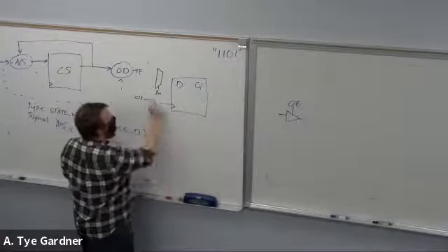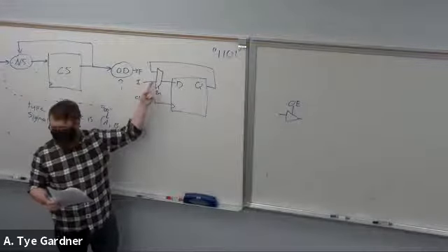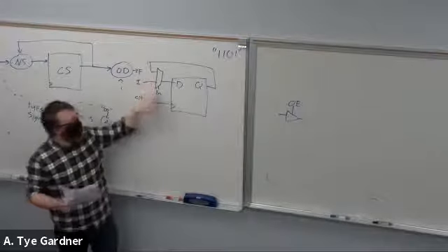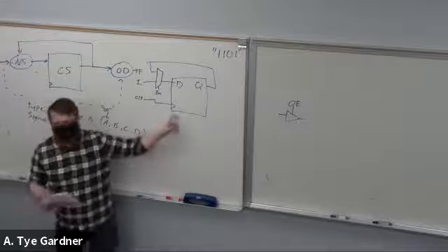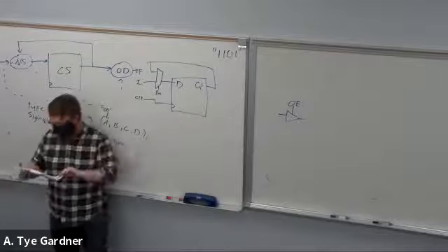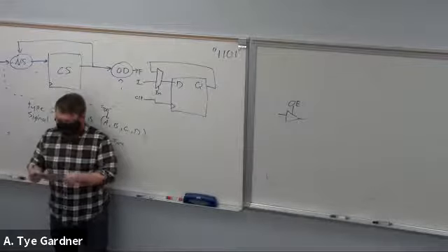Right, what happens is if I'm not enabled, when the rising edge of the clock happens, I just take the previous value. And if I am enabled, then I pass I in. That's the right way. This is the one that a lot of people missed. Maybe a third of the class. Okay.